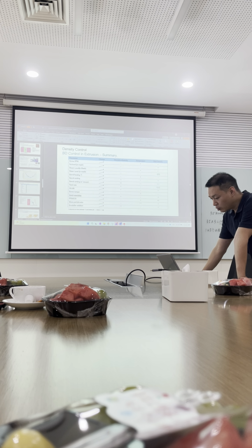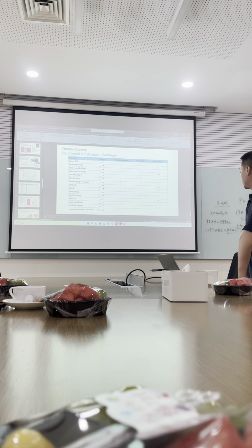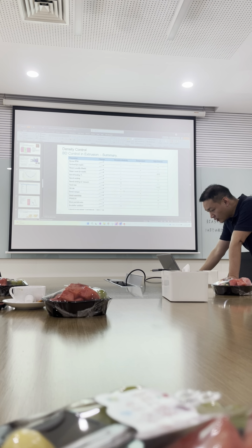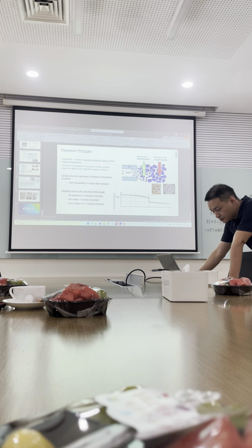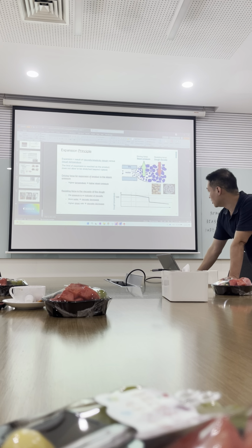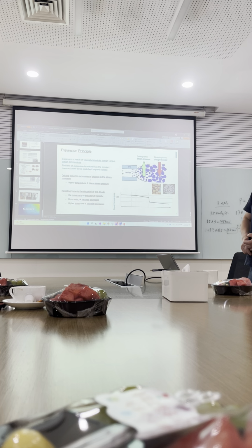And also, for most of the points I have mentioned here, for the opening area die, with higher opening area, it means the pressure is lower, right? And the bulk density will be higher, right? Easy to understand. So this is why I say if you understand this, then you can adjust most of the parameters for the extruder.